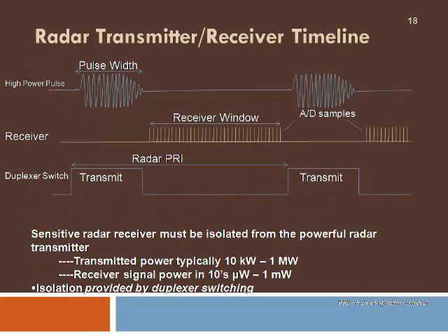Here we see that a high power pulse is transmitted by the antenna, and now the antenna will be waiting for the echo from the target. This echo will be received by the same antenna, and it should now be directed to the receiver, and after a certain time the transmitter must again be connected to the antenna to transmit the next pulse.